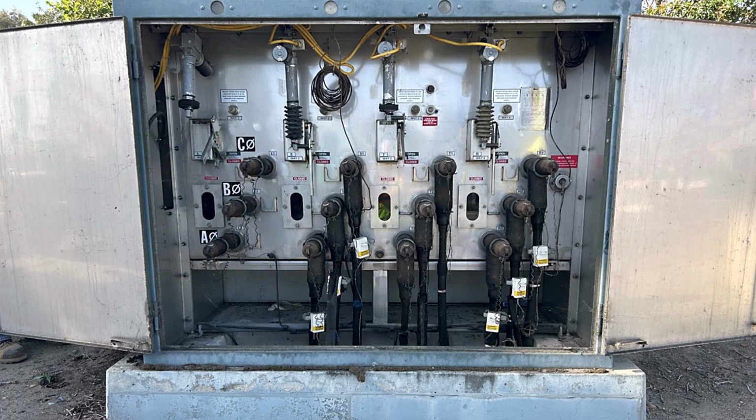You can clearly see the cables connected to way 2 coming up from the underground conduit system, as well as way 3 and 4. The switch levers that open and close each of the switches are located right here, one for each way. The little glass windows at the bottom enable a line worker to look inside the cabinet and actually see the switch contacts to ensure that they're in the desired position. This is called visible disconnects and is a safety feature for line workers who are operating the switch.